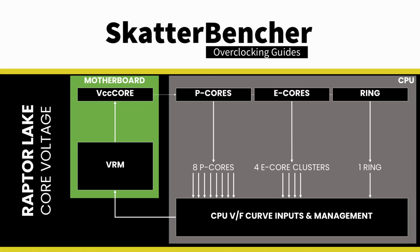The final important information is that the CPU P-cores, E-cores, and ring share the same VCC core voltage rail. Effectively, it means that when the P-core runs 60x at 1.465 volt, it also runs the E-cores at 1.465 volt, regardless of its frequency or VF curve. Now that we know how the Core i9-14900K works, let's get to the overclocking.